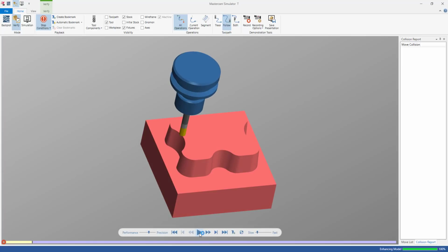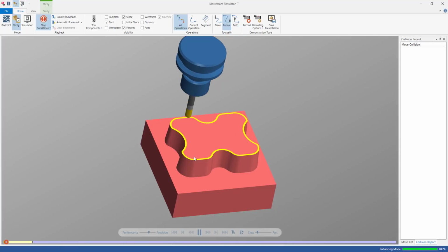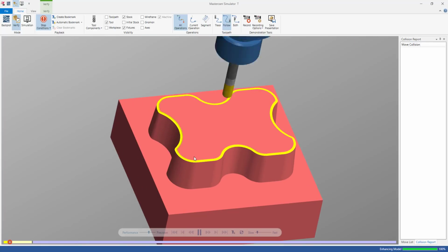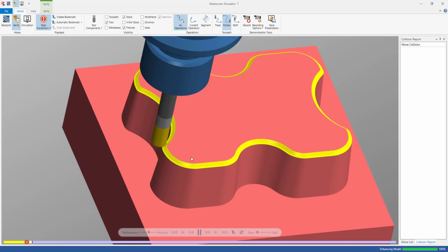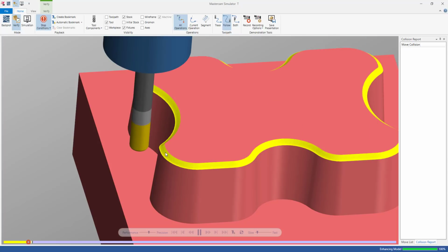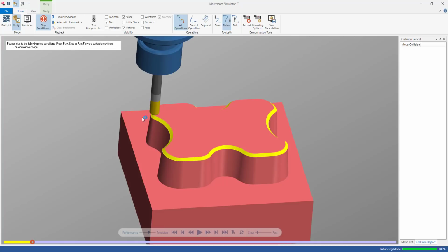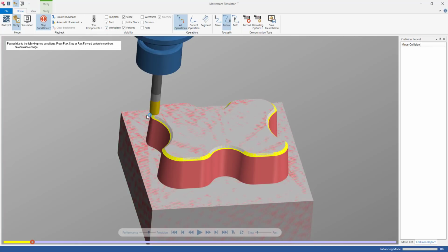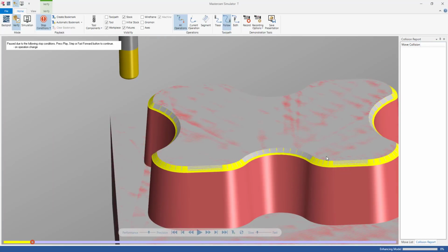It's a bit slow. Yeah, this is the first toolpath. We cut the chamfer on the top of the part. And I'm going to turn on the workpiece so you can see it's completely cut and no collision. The tool is in contact with the part, with the workpiece. Yeah, you can see no collision. It's the right contact.